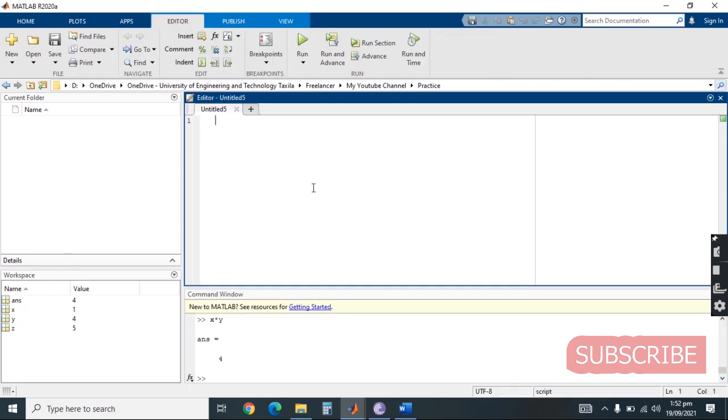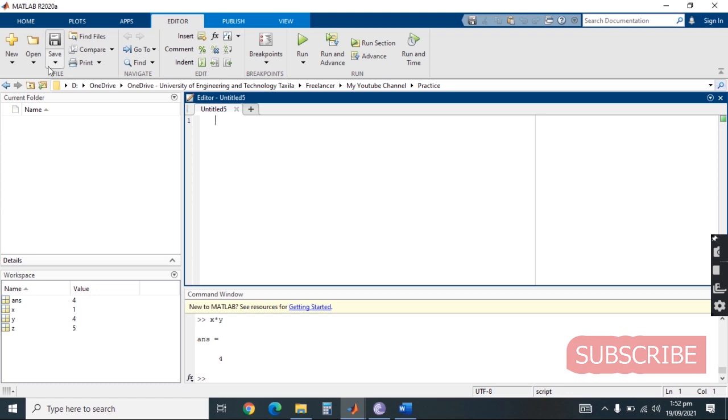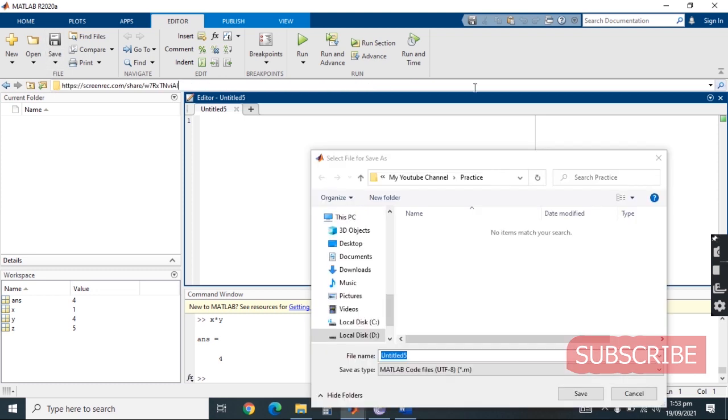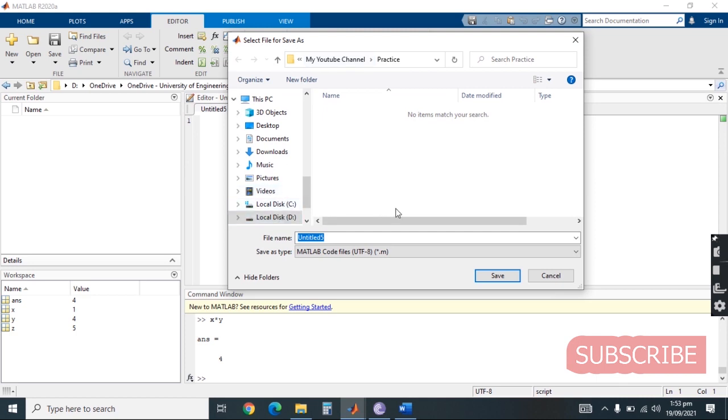Now we will do the same functions in the script window. When I press the script button, it opens the editor window, in which we can type our programs and execute the statements. The output appears in the command line view. First, we have to save it. When we press the Save button, it saves the file by the name of untitled file, in the practice folder.